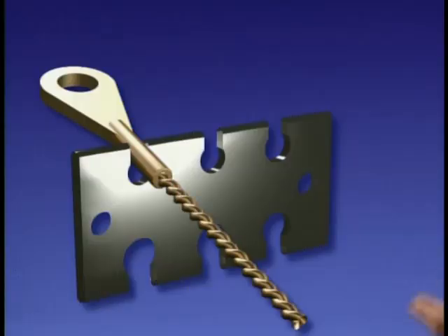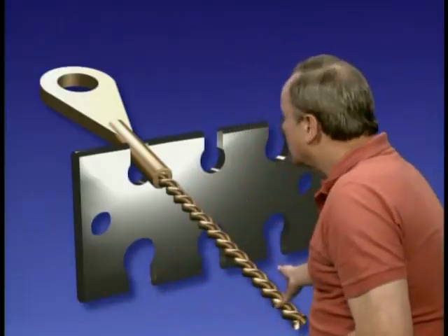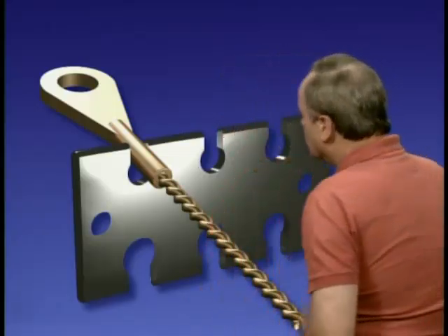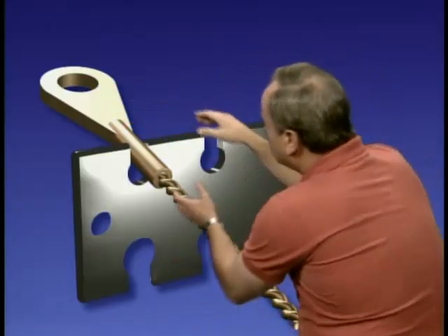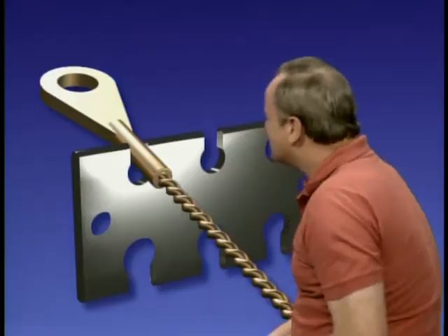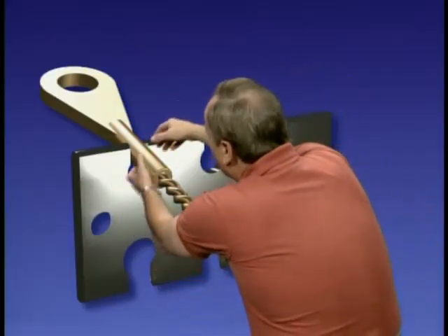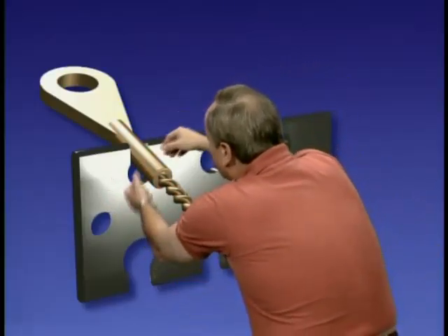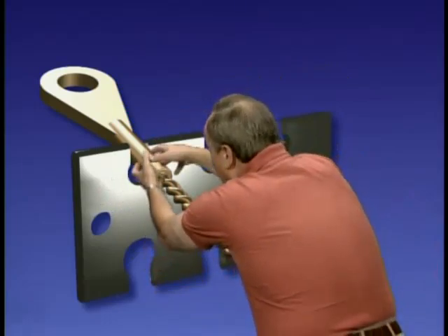Now let's assume that you've just inspected an aircraft and one of the things that you have decided is that you need to replace the control cables. Well, when you do that, one of the things you'll also need to do is reattach a terminal to a cable. Now, how are you going to do that? Well, these days the way you do it is press it on, or what they call swaging it on. This is called a swaged terminal.